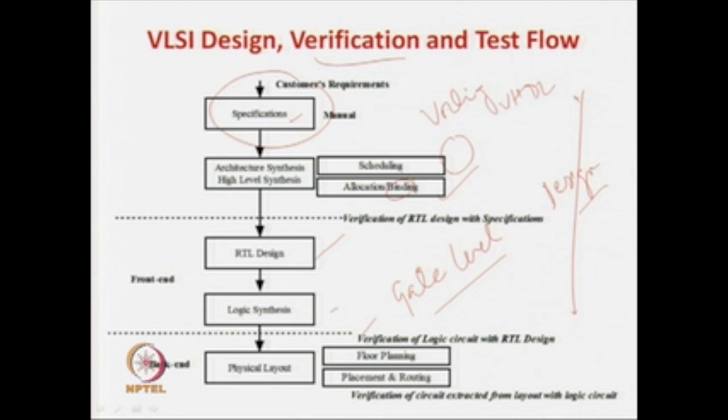Like in this case, we can get a control and data flow graph kind of a structure. After the logic synthesis step, we get the Boolean gate level circuit. In this case, we get operators in some logical time steps, as we have seen. So, for the same specification, like addition or control, we have different representations.